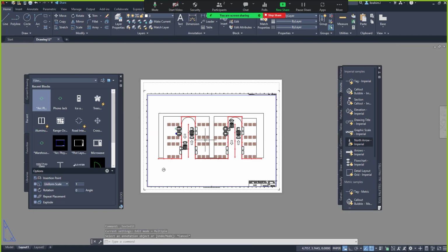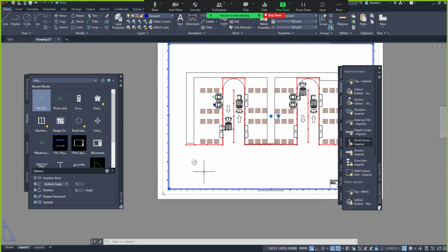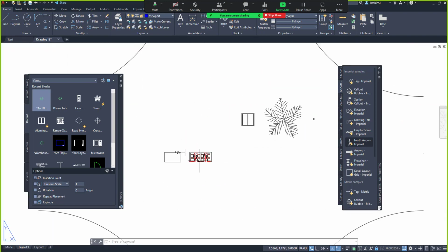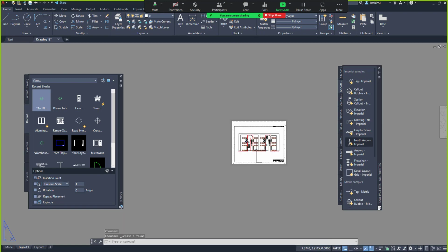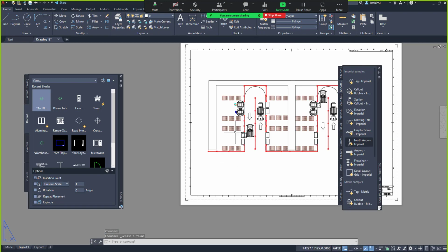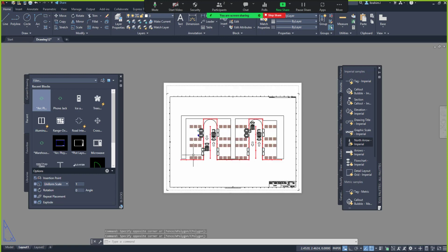So this is all about the layout. But like I said, for this viewport that I imported, by default there's a viewport that comes with it. For that, I copied everything under that layout, converted it into a block and brought it here. That viewport that comes with it is the one showing everything that I have here. Can you see this viewport here? It's showing everything on the workspace again. When I select the viewport itself, because I've ungrouped and excluded, I'll click on delete. Can you see that part has gone off again? Because we have already created a viewport here by default. We have created a viewport here ourselves.